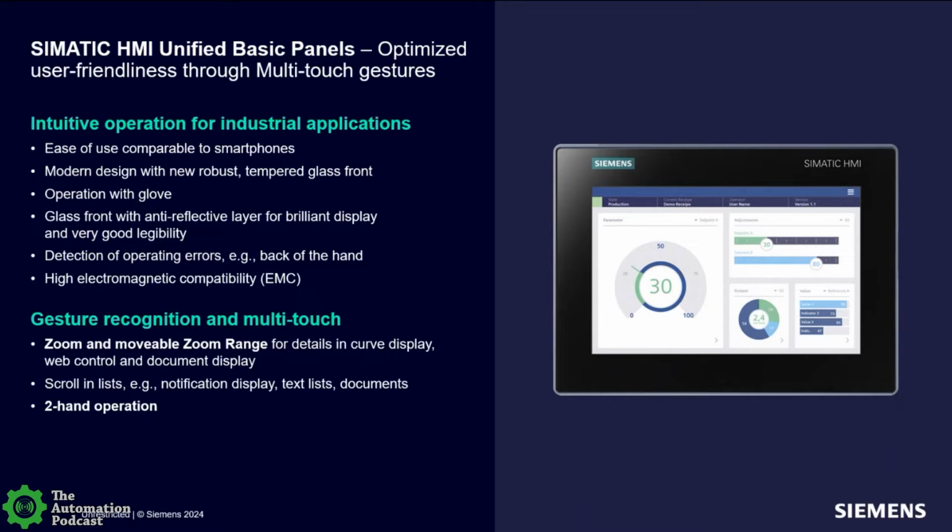On a 4-inch and a 7-inch screen, it may not be a good application because, I'm sorry, my hands are big. I can actually span a 7-inch screen. But the 10 and 12s, it may become more of a good use case for you to put a button in the corner to say activate the slider, and the slider on the other side, and drives the operators to be in a safe spot on the screen away from any movements of things on your operation. So just two-handed operations are capable with unifieds as well.